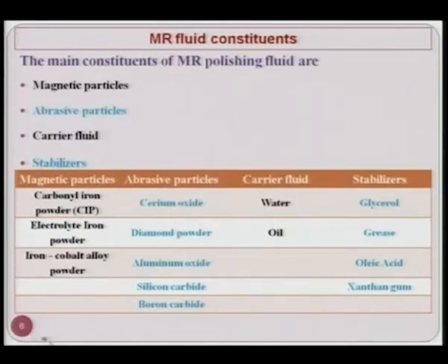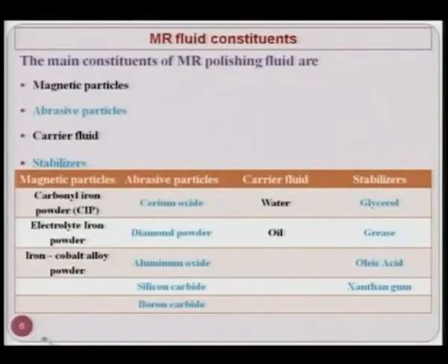The selection of abrasive particles will depend upon the type of workpiece material that you want to finish. Then carrier fluid: in many applications, specifically when you want to finish ceramics, single crystal ceramics or others, water is used as the carrier fluid, and in some cases you can use oil where you cannot use water because of certain constraints. Then there are certain stabilizers which are used, namely glycerol, grease, oleic acid, and xanthan gum.